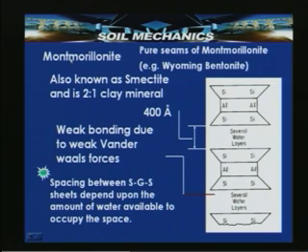And as we said, another mineral is montmorillonite. This is called a 2:1 clay mineral and is also known as smectite. Pure seams of montmorillonite can exist in Wyoming bentonite and in Australia. So, this montmorillonite is a 2:1 clay mineral because two silicate sheets sandwich one alumina sheet or gibbsite sheet. And because of this,